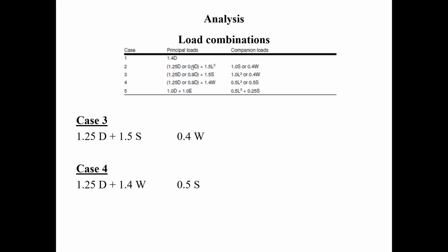No, we did all of this. Like in the problem we did in class, we said that the wind load was 0.833 kPa. Well, how did they come up with that value? I just showed you how they come up with that value. And then for serviceability, the wind load is 0.625 kPa. Well, you take 75% of that value, that's how you get it for serviceability.